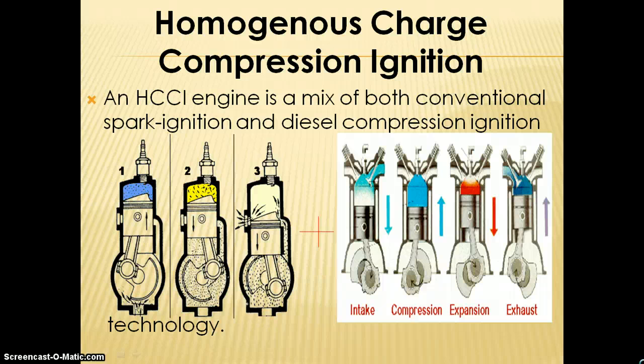Now, for new alternative that seems to be helpful in reduction of pollution, the homogeneous charge compression ignition is the ultimate combustion method for achieving both CO2 reduction and clean exhaust using an ignition of gasoline and most alternative fuels, especially dimethyl ether, as in a diesel engine. Well, this engine is a mix of 4 and 2-stroke engines. So how does it work? The HCCI.